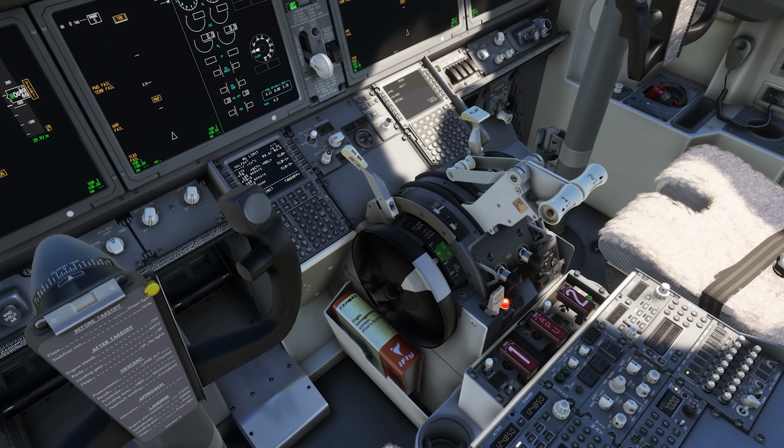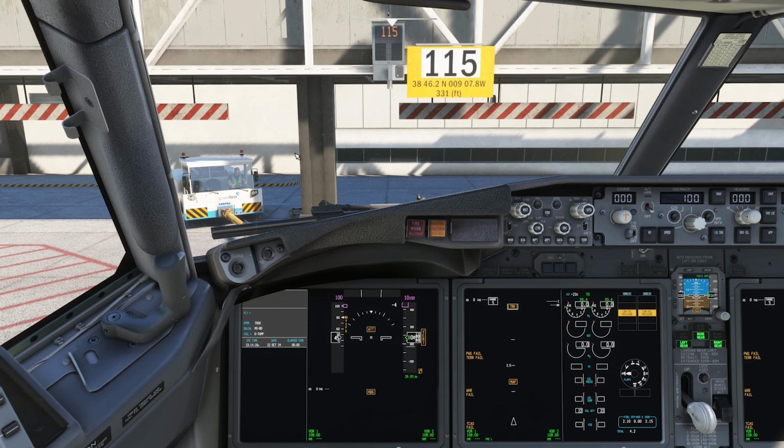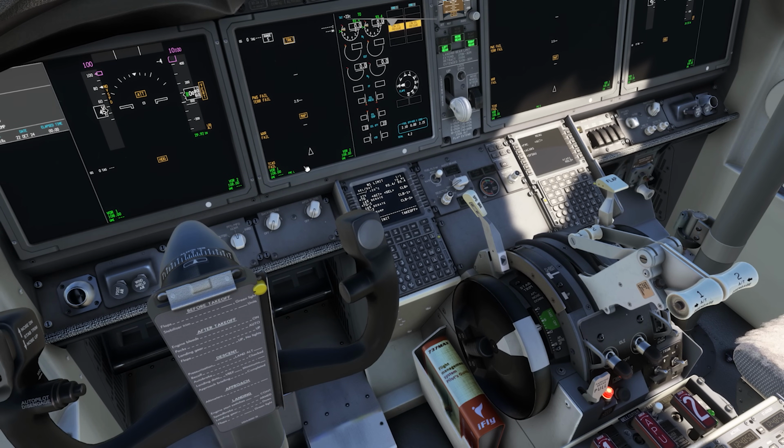One of those features is something I think you see in the 737-600 and 700. It's called MLA, or Maneuver Load Alleviation. Basically, when the aircraft's performing high G loads, 1.3 G to minus, or I think 0.3 G, it'll automatically stow the speed brake slightly to reduce loads on the wing. You won't see the speed brake move, that just happens on the wing, completely automatic. It's transparent to the flight crew.